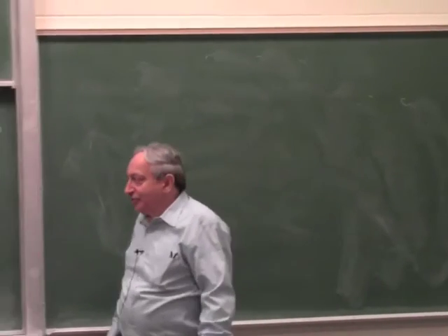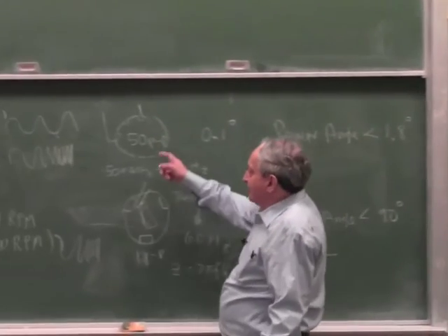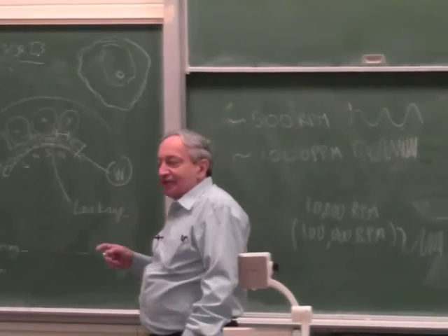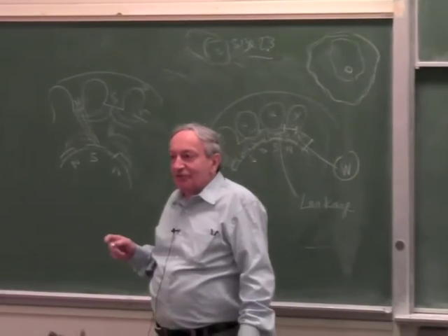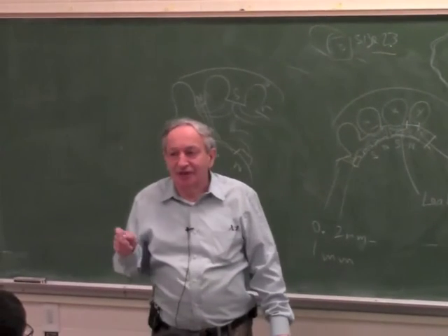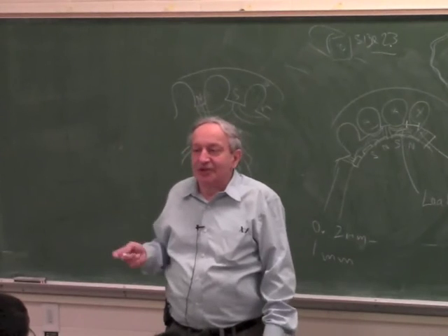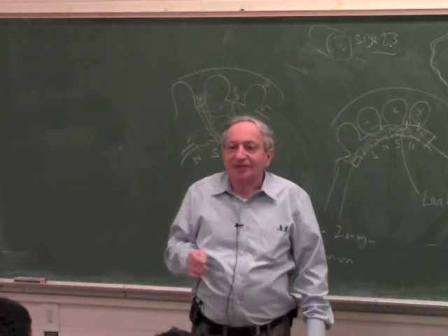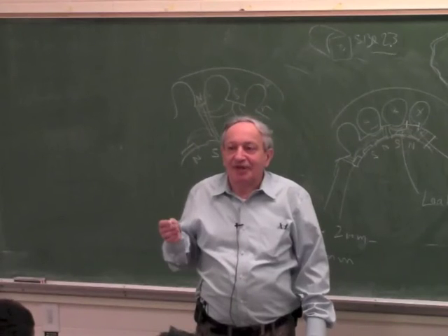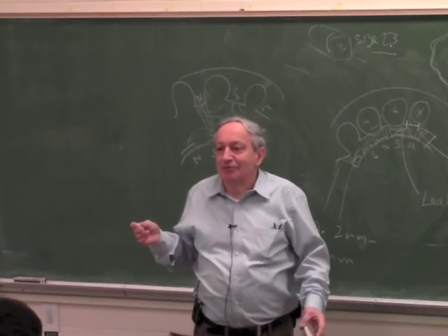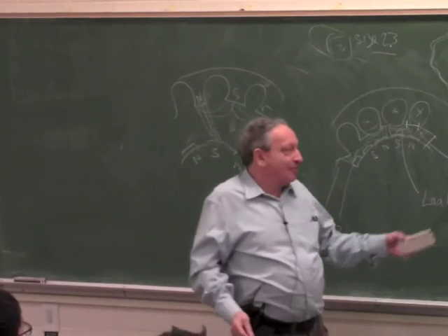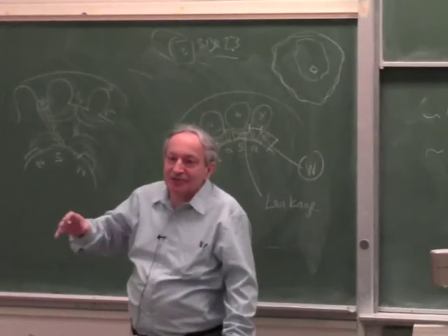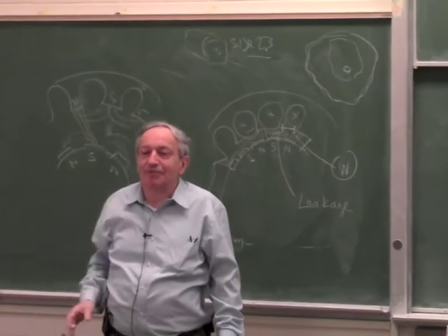So one other thing you have to remember, the fact you can run a stepper motor open loop is a huge time saver in development time. Because if you have to design a fully closed loop servo, versus a stepper motor, which you just give a command and it goes there, the development time is almost 10 to 1. In a stepper motor, there is just a computer which commands a microstepper. The microstepper pulses the stepper, and you're done.